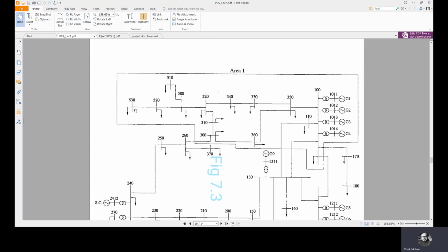Of course, these are PQ buses because these are load buses. So at each increment, whenever we increment P with some delta P, the new P value assigned for the PQ bus is P plus delta P at each bus. Then we will again run the load flow, and then we will get the unknown variable values. At each stage, we are doing the same thing.